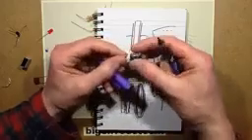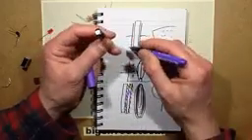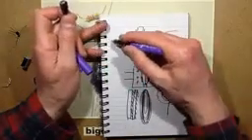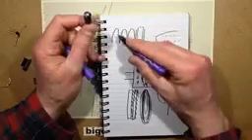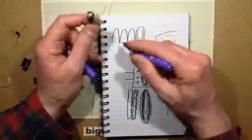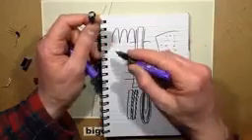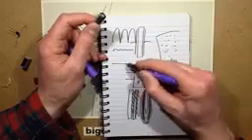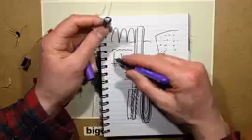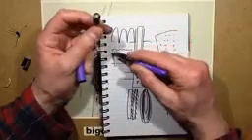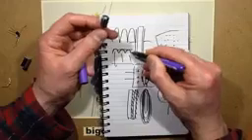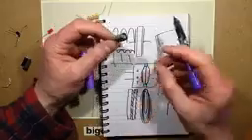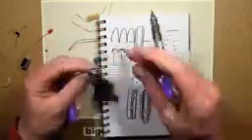When you get the large values like this, they're usually used to smooth ripples. So say for instance the output from the mains was rectified, and you had a big peaky full wave rectified AC waveform, which is like the two sides of a sine wave. Then by putting this across that, it reduces it to a very slight ripple and a nice smooth DC voltage. And as that capacitor dries out over time, that ripple will get bigger, and it ultimately starts causing problems when it dips down so low that the electronics can't sustain normal operation. And that's when you have to change the capacitors.